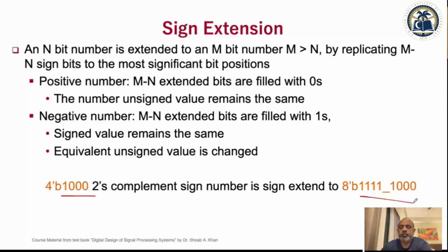So you have to extend it by replicating the sign bits. So -8 as a 4-bit number is 1000, and -8 as an 8-bit number is 11111000.